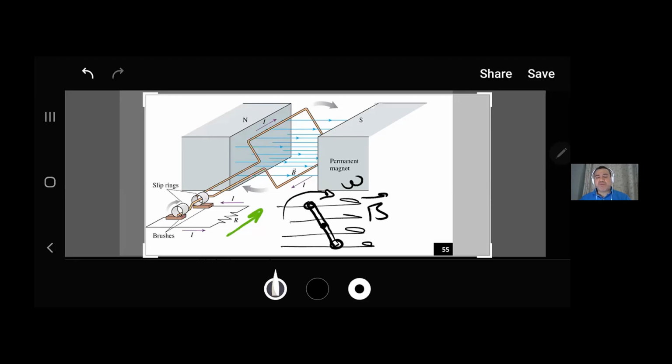Basically, this means the opposing magnetic field is going to be in the opposite direction, and based on the right-hand rule, the current is going to enter at the top and come out of the screen at the bottom. If you look at the current, you will see that what we have concluded was correct. Yes, the current is entering at the top and leaving at the bottom.